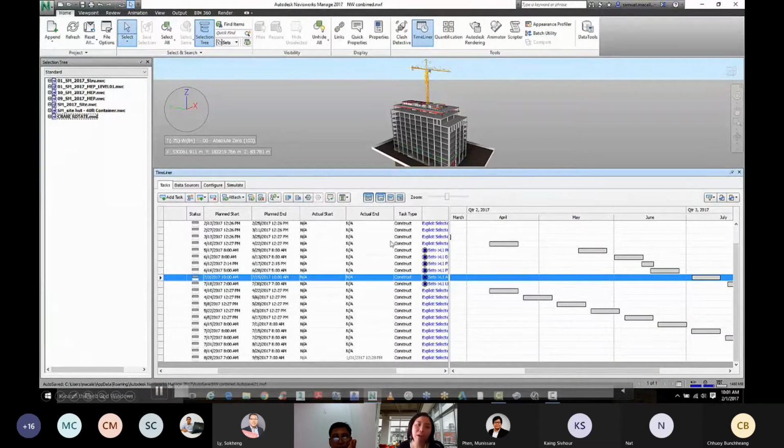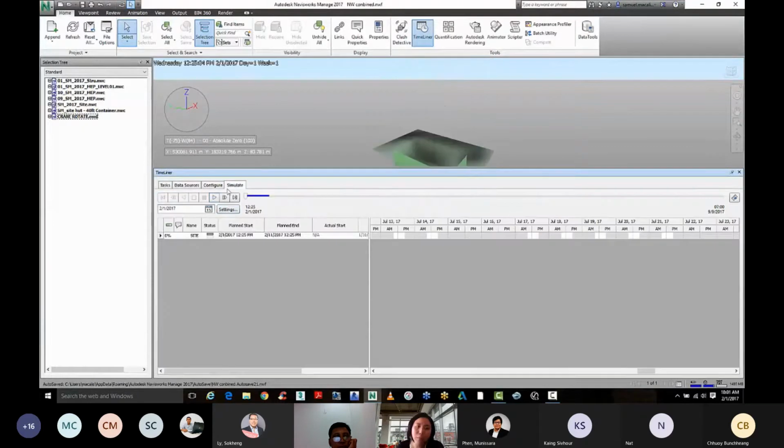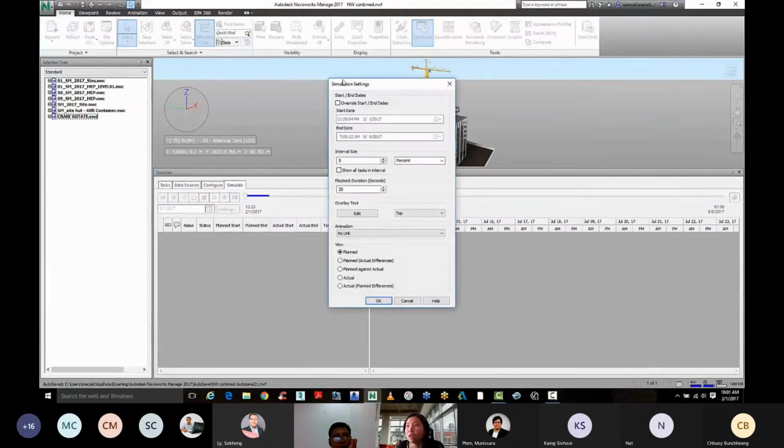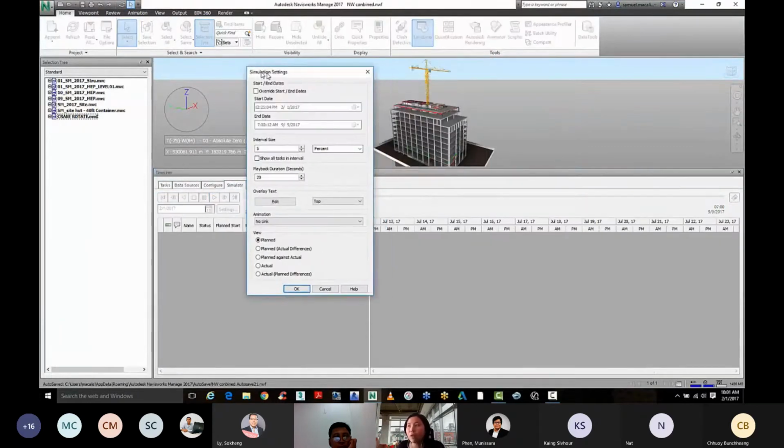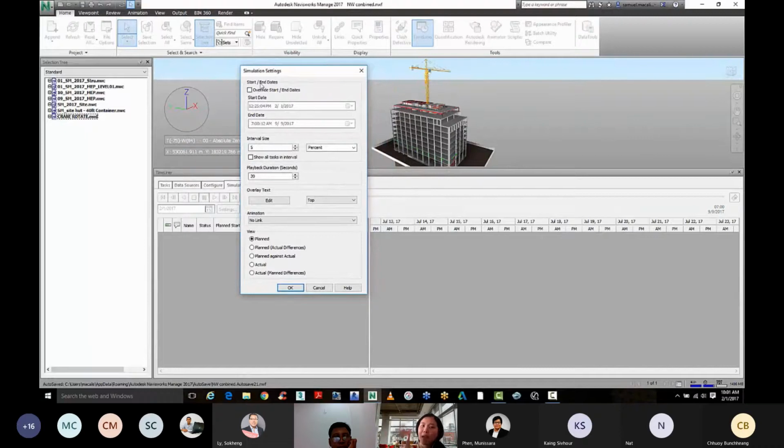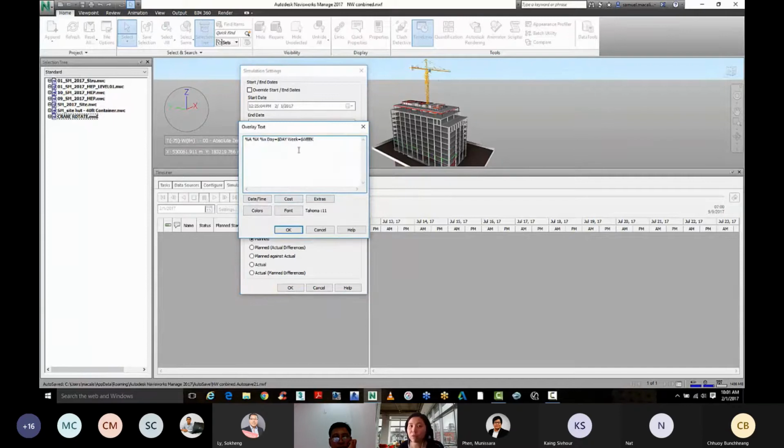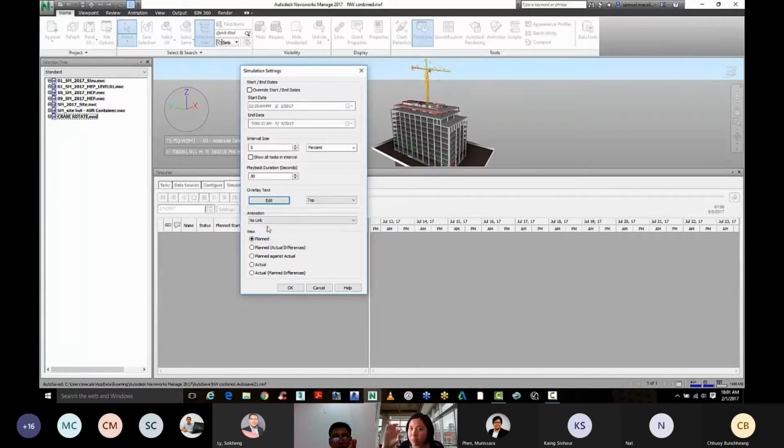So if you actually have a project, what we call a work program in your project, you can put the work program directly into your Navisworks, and then from there you can link the different elements of the model into the work project. Because let's say the work project says on February 3rd, you're supposed to have the structural slab on level 5 created. So you can link that particular level 5 slab with the work program that actually says that this is the work that's to be done for February 3rd.